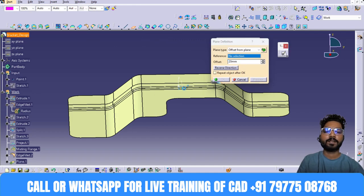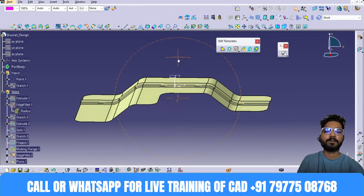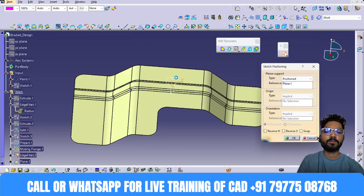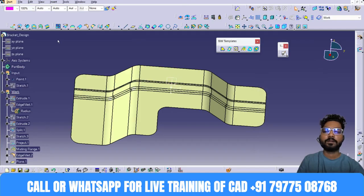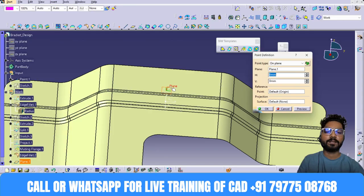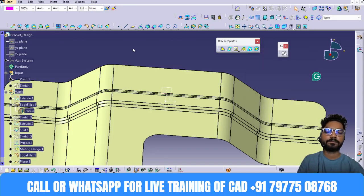On this plane, a 120 mm offset plane I am taking. And now here we'll create one position sketch, or we can take a point directly with the point on plane option, and on this plane we'll take one point, enter.